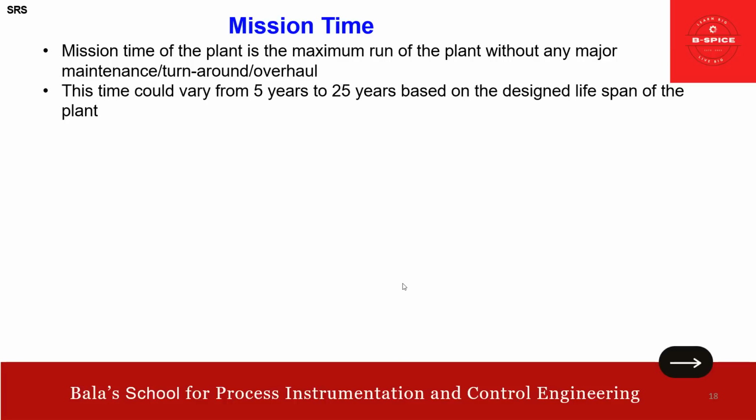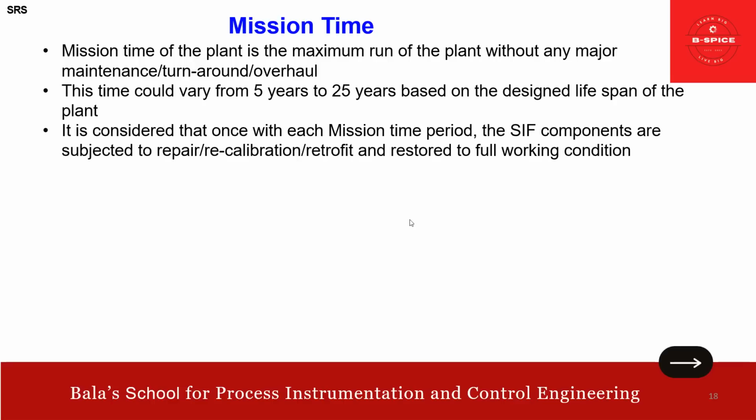This time could vary from 5 years to 25 years based on the design lifespan of the plant. It is considered that with each mission time period, the SIF components are subjected to repair, recalibration, retrofit and restored to full condition. Okay, this is the mission time. So that is also something we need to cover here.